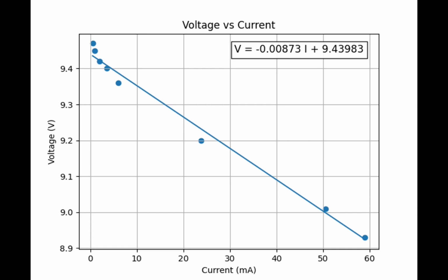The errors in the experiments were maybe caused from the multimeter could not give exact results in such a small current, the resistors were heated up when connected to the battery because of the current, and the heat changed their resistances, especially for low resistance resistors. This can be also seen in the graph too. And the resistances of the wires, which were considered as zero in the theory. That was my conclusion from this experiment.